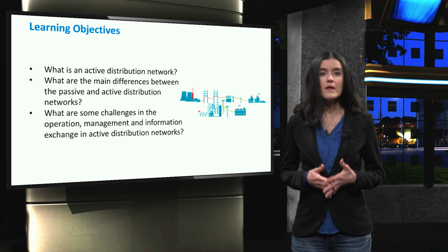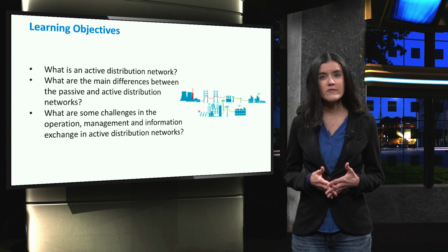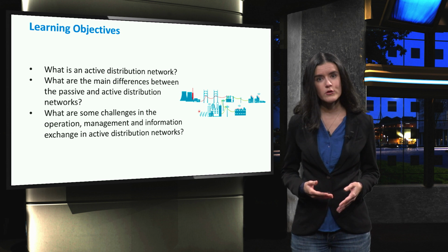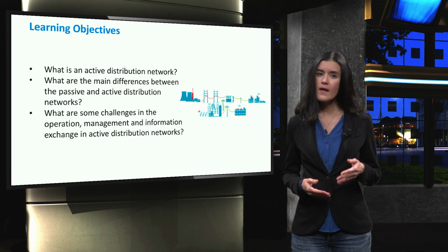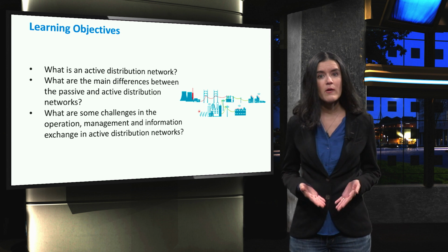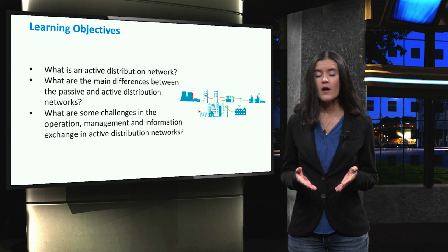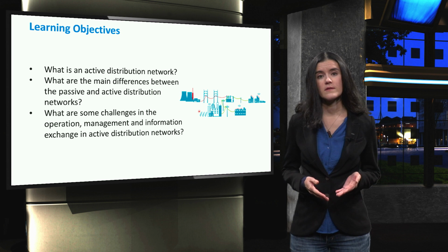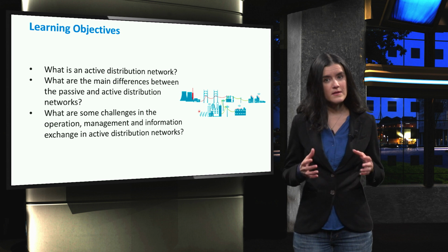Under this scheme, distribution system operators have the possibility to manage the electricity flows using a flexible network topology. A very important characteristic of such networks is that the flow of power becomes bidirectional. Also, decision-making and control become decentralized, instead of being performed at a centralized authority.